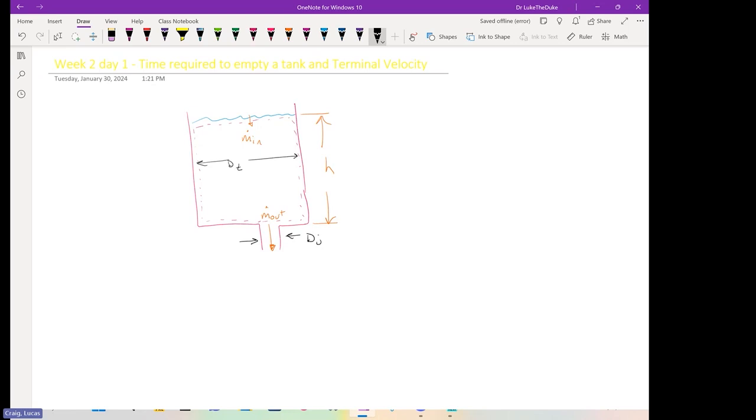You turn the water on, it fills up, and then it could empty in the drain. So mass flow rate or volume flow rate? Almost. A times V is volume flow rate because the units are meters cubed per second. Mass flow rate is rho AV because it's density, area, velocity.